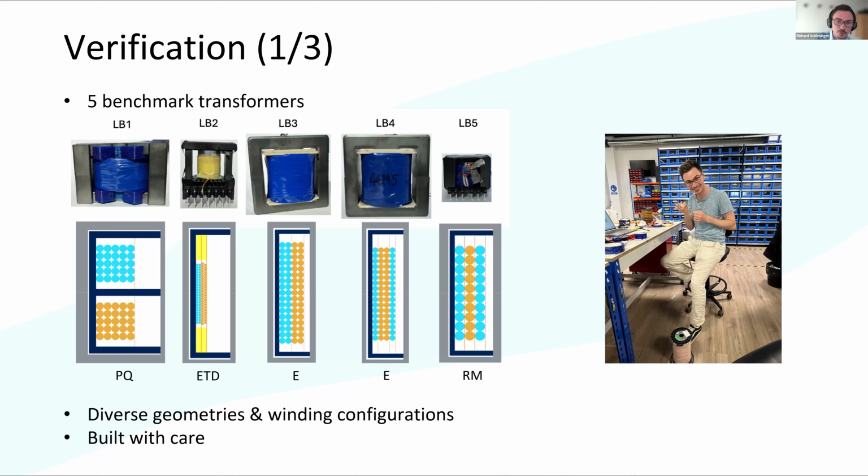In a high frequency transformer, how can we decrease the leakage inductance? Well, you can decrease the leakage inductance by putting the windings as close as possible, because then you minimize the space where the magnetic energy is stored. And also you can choose fewer turns because the leakage inductance is proportional to the number of turns squared from the side you measure it.